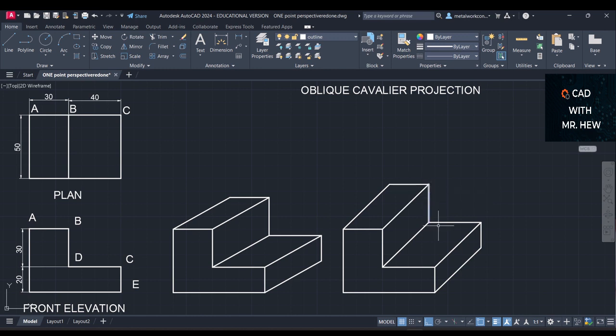Now, we don't normally draw hidden details in a pictorial drawing, which is the other side. We're just working with the part that we can see at the front, unless the object is made out of glass or transparent plastic. Is that clear? Here we have the 30 and the 45, same object, but you're drawing the receding lines at different angles relative to the horizontal line.